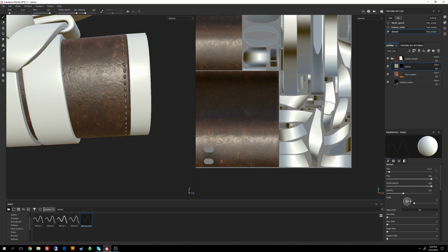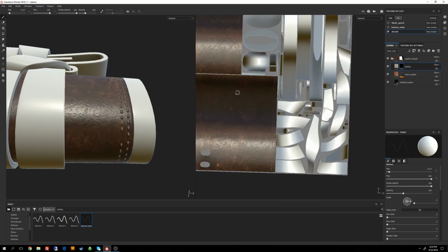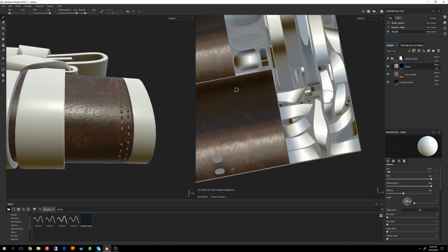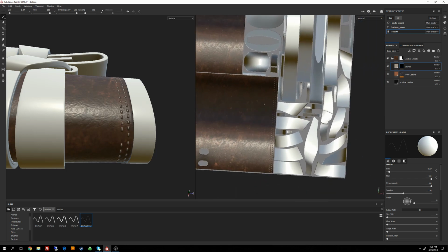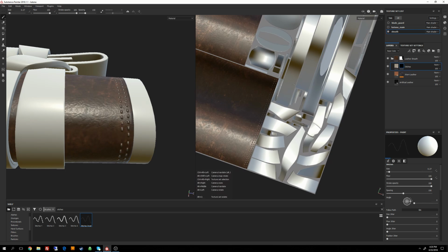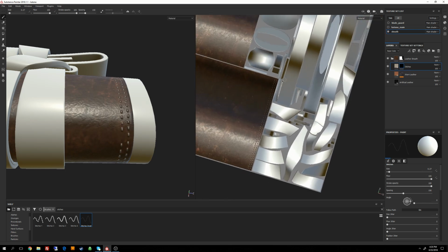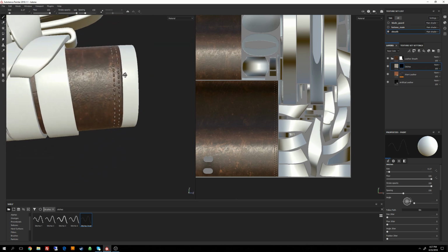I'm going to come over a little more to the left and add a little space in between. You can see it did that again. I hate when this happens. If you have this problem where you've rotated the view like this, hold Alt down and then hold Shift. That'll constrain it back to a square view. Let's undo that and reapply it. That's a little better.